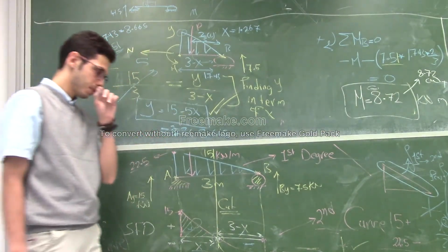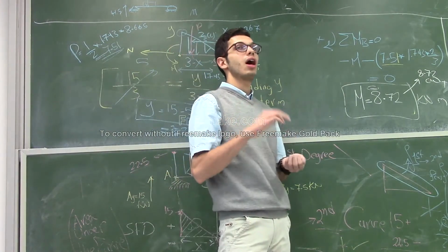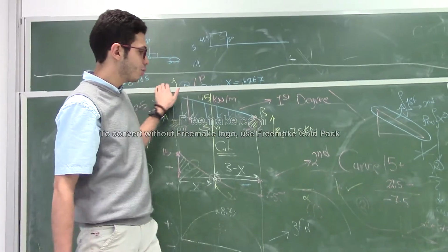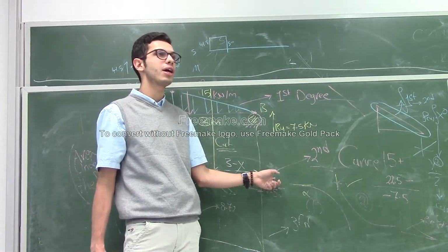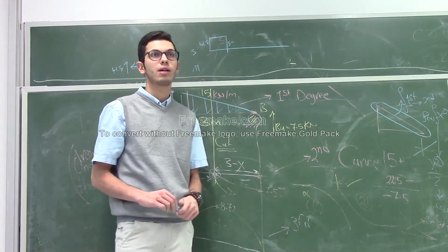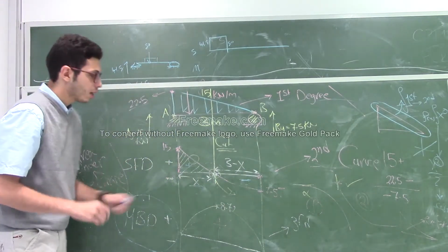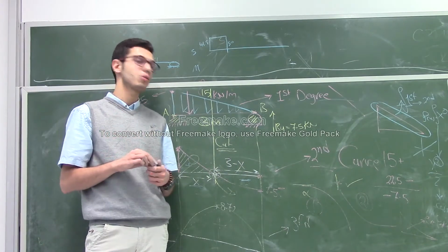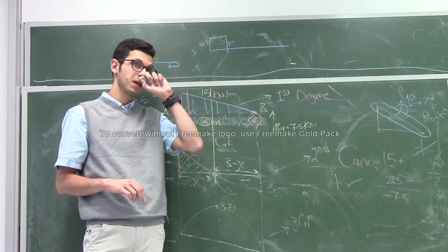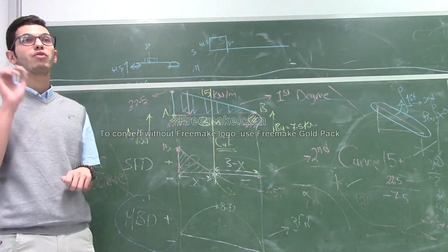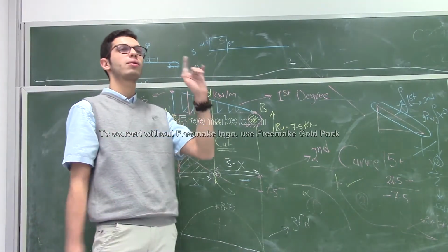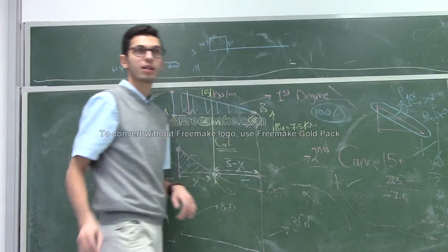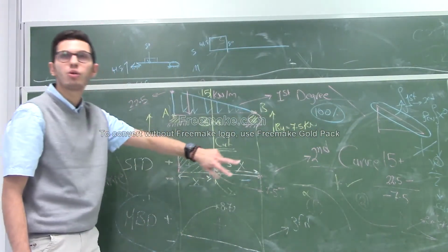And by the way, as I said before, the shear diagram should end with a 0, right? And the moment diagram should also end with a 0, right? But if the shear diagram ends with a 0, that's not necessarily a sign that your solution is correct. If you want to say 100% that your solution is correct, both of them should end with a 0.